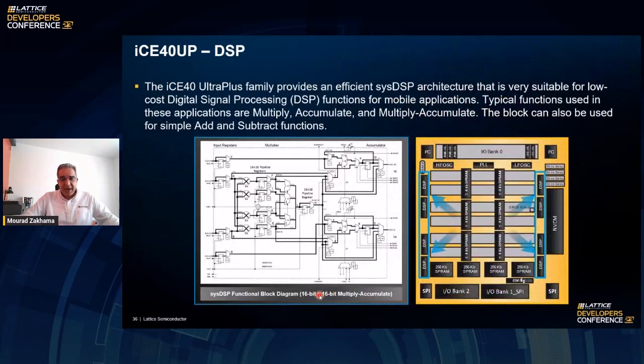DSP blocks, it's an eye chart that we see here. I will not go through the details of all this, but just making sure that you understand that it's a very complex block with hardened multipliers that are built in, and also input registers, pipeline registers, and some flexibility in terms of how to cascade some of the blocks that you have there.